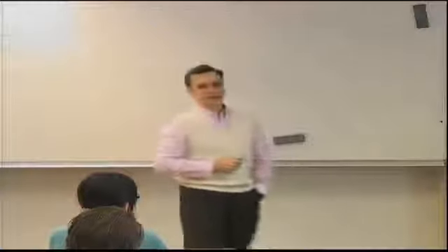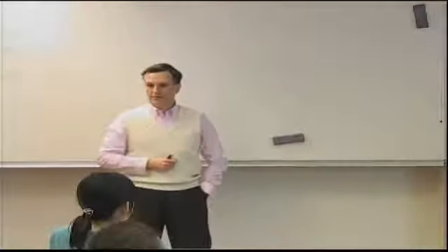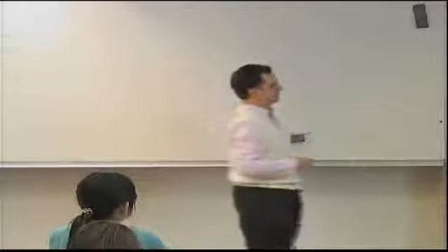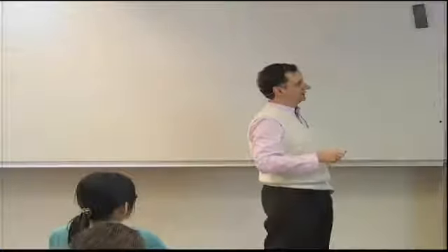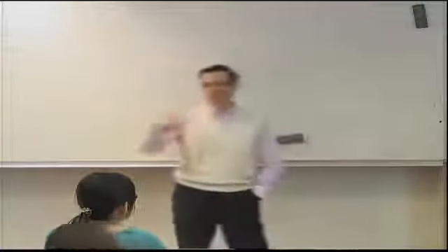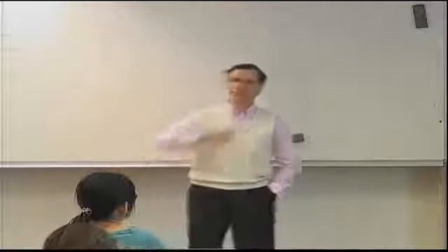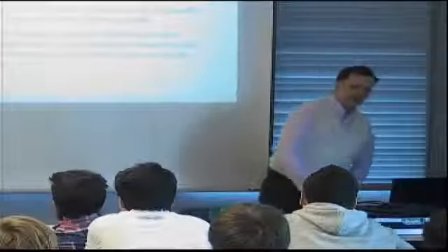So all this improvement in buckling load from one laminate to the other has translated to a tiny 3.7% increase in Nx, which would be a 3.7% increase in your stresses and so on. So the message here is don't assume that buckling load is an indication of good post-buckling performance.